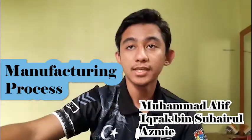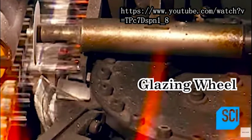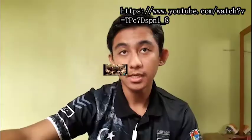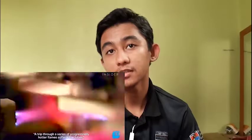The process of making an incandescent light bulb. First, a machine cuts the glass tube into specific lengths and loads it into a glazing wheel to smooth the surface. Next, the glass tube enters the flare making machine, which heats the tube to make it malleable and stretches one end into a flare shape. Next, load 2 copper lead wires into the flare and insert in the exhaust tube. A hotter flame softens the tube. Then press to enhance the wire in glass.